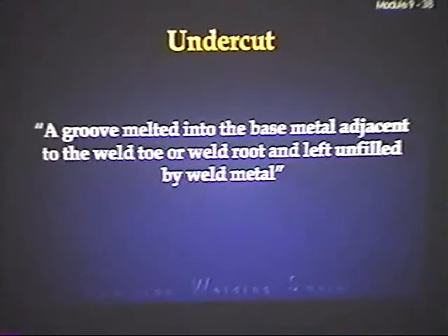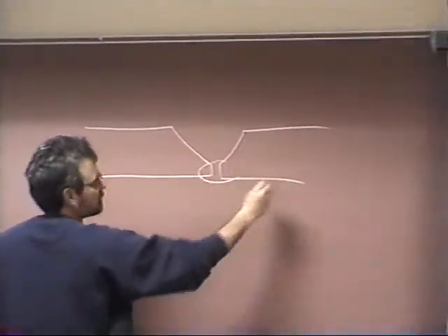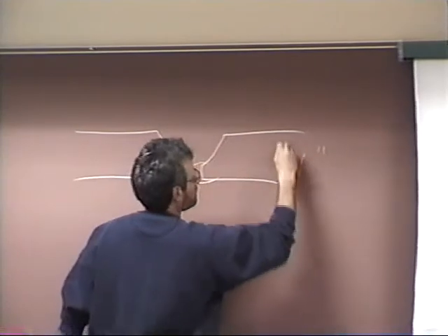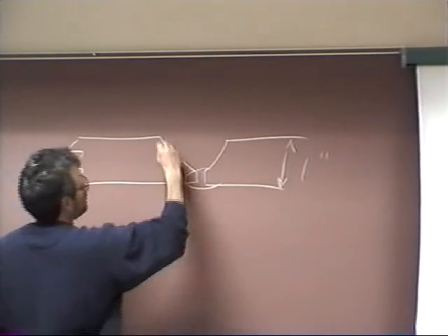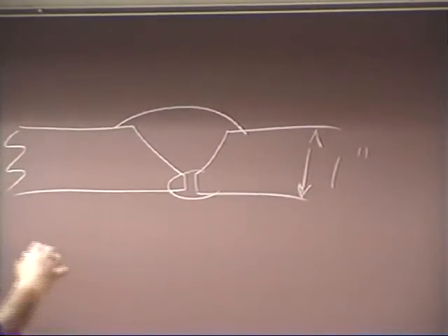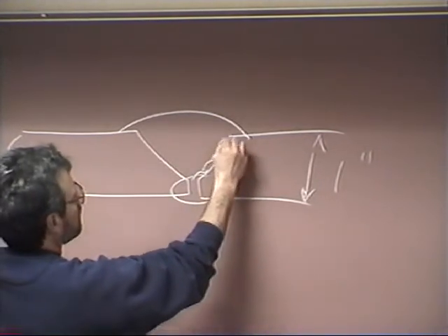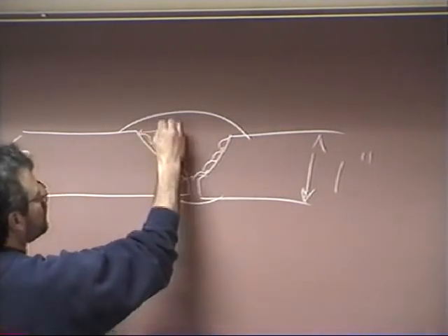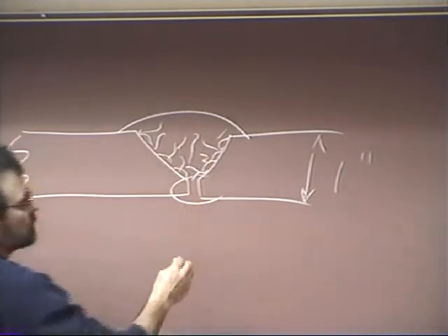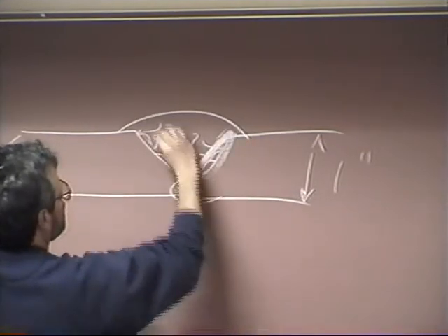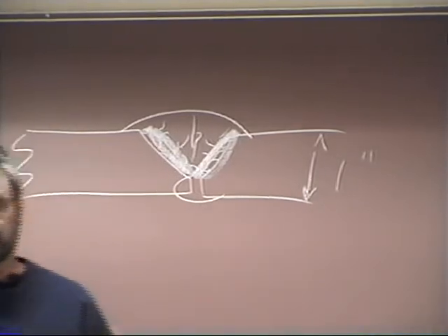Let's say you have a weld like this, and let's say it's 1 inch thick. Okay. Well, that's quite a bit of metal. So you fill that baby up. Well, what happens to the weld metal when it's cooling? It cools from the cold parent metal in towards the center of the weld, and that's what our textbook says. So it's cooling out here, but it's still hot in here. So you have a disproportion, a non-uniform type of cooling.